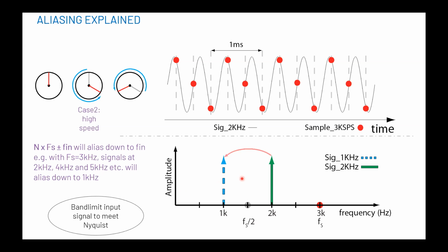We have to make sure that our sampling frequency is always greater than twice the maximum input frequency. Now, we could always say that my information is always going to be at 1 kilohertz. But you have noise, and several other disturbances along the wires that could cause a high frequency signal in your inputs. And this would cause aliasing. So the best way to do it is to band limit the input signal using a low pass filter. Now I hope this is clear. If there are any questions, we can take them at the end.